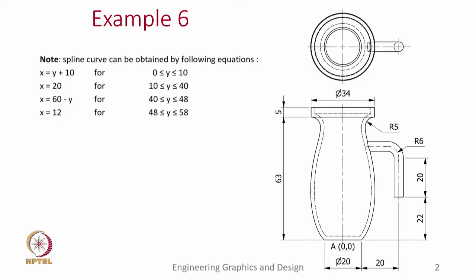Here is a vase we are trying to create. As you can see, it has a handle to the right, we need to create that as well. So, let us look into the front view and the top view and try to understand what tools we may need to use to create this solid. These dashed lines indicate that the interior is hollow, which means we will be using the shell tool.